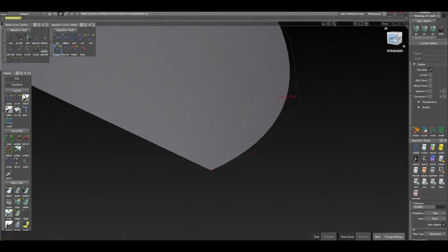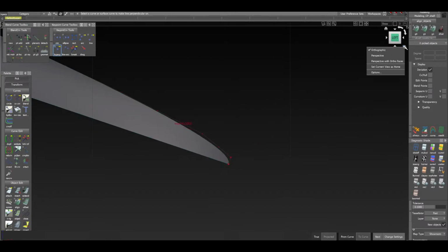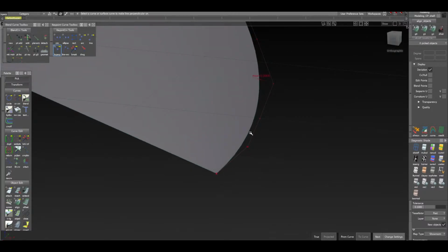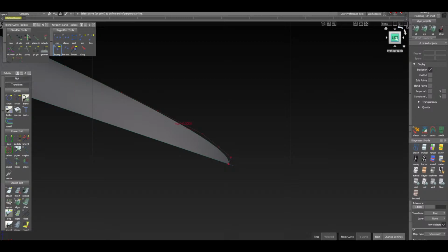So what we're going to do is use different views. Again, I'm working orthographically, not with perspective. This is orthographic. Well, first I have to instruct the tool that I'm following the fit curve. So I'm going to hit Control, Alt, left mouse button. I'm going to pull all the way backwards here to the base of the fit curve. Okay. And then orthographically, I'm going to hit the left view, until it's green. And then I'm just going to pull. Okay, it's working laterally, which is fine. So that's fine.